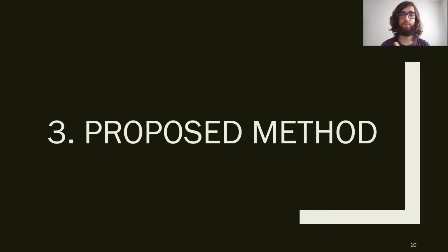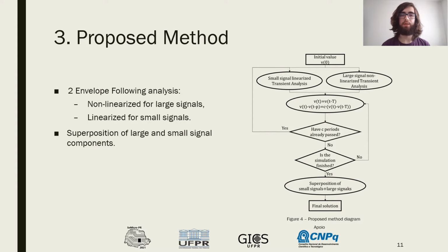And now the proposed method, the combined nonlinear and linearized envelope following. The CNL-EF uses two envelope following analyses, one nonlinearized for large signals and a linearized for small signals. After both simulations run in parallel, they are added together, following the superposition theorem.